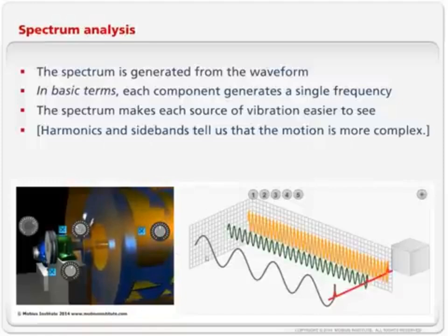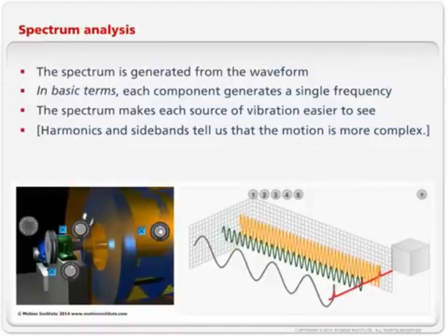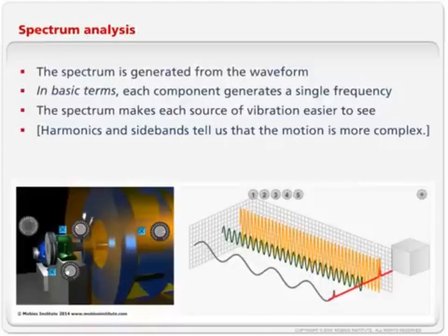The up and down or y-axis is the amplitude of the vibration. But each of these represents a frequency, and our spectrum, which is the most common tool used by vibration analysts, is as if we look at the vibration from this axis. If you can hopefully see my mouse moving. And so if I change the speed of the machine, you can see the waveforms all change in frequency. If I change the amount of fan vibration, you can see that one go up. Oops, I went too far. And you can see the changes, or the unbalanced vibration, let's say.